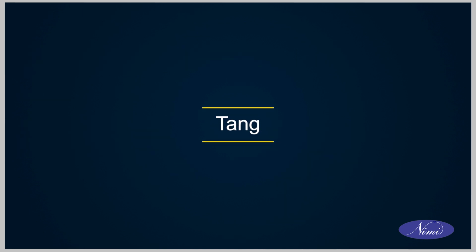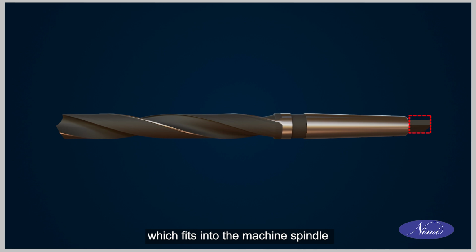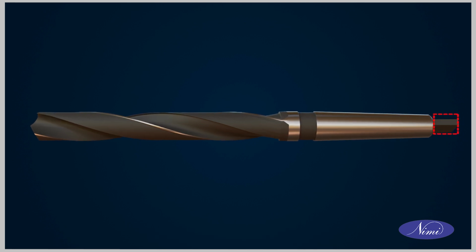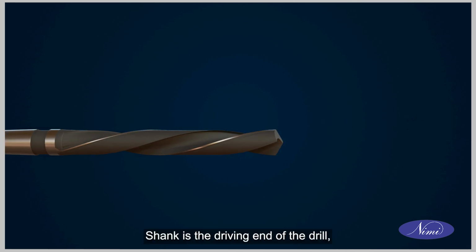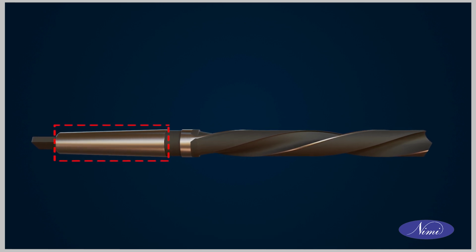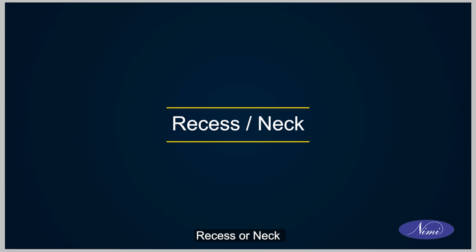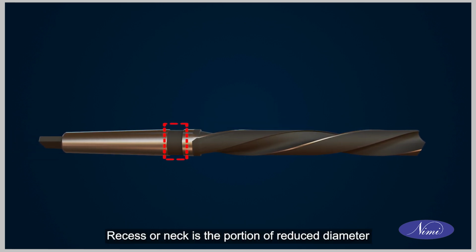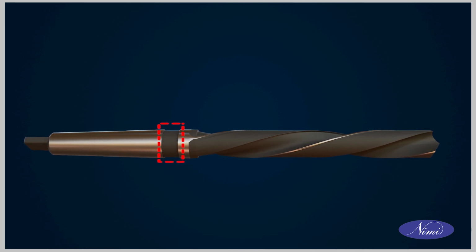Tang. Tang is a part of the taper shank drill which fits into the machine spindle. Shank. Shank is the driving end of the drill which is fitted into the spindle. Recess or neck. Recess or neck is the portion of reduced diameter between the body and the shank.